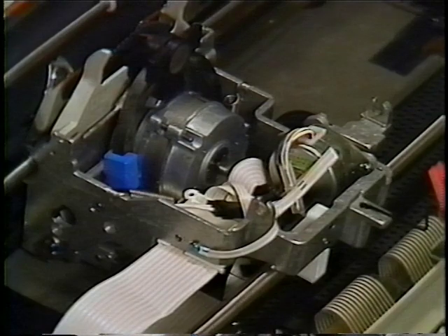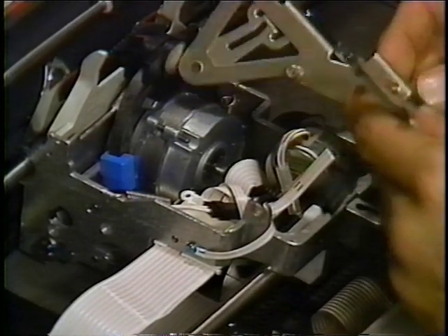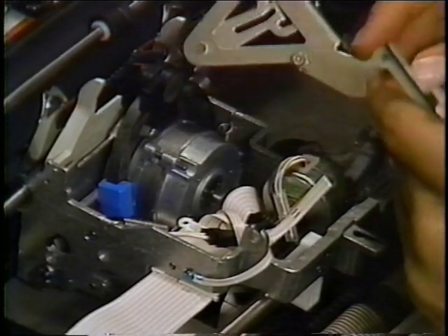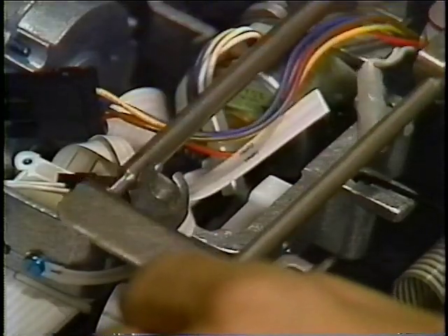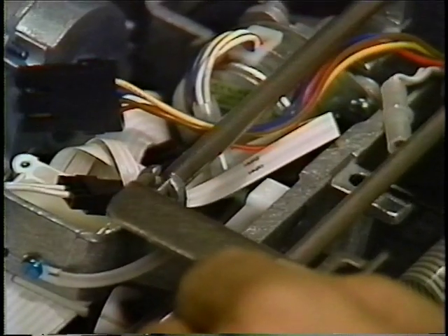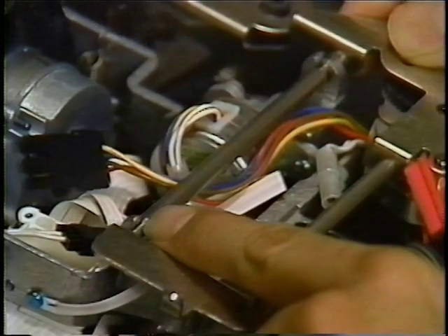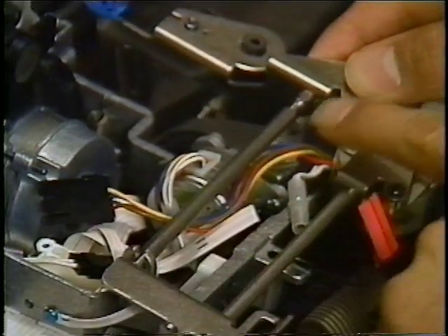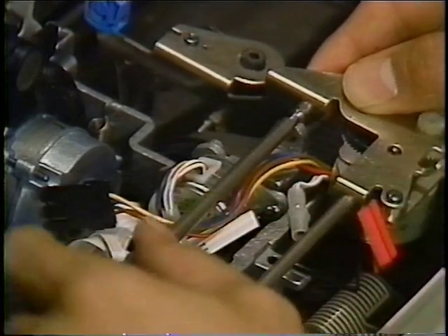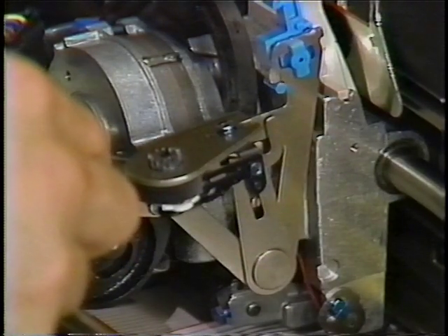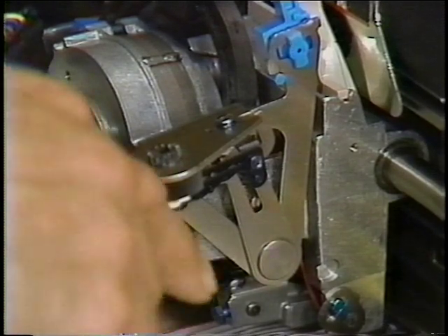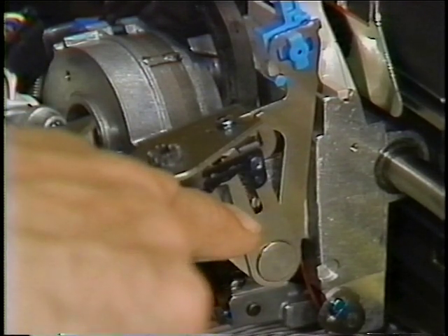To install the ribbon plate, check that the cam follower roller is in place on the stud, then place the ribbon plate on the carrier so the narrow areas on the ribbon plate shaft fit into the cutouts on the carrier frame as shown. Make sure the correction feed cam follower stud fits through the slot in the correction feed arm, then slide the ribbon plate to the left.